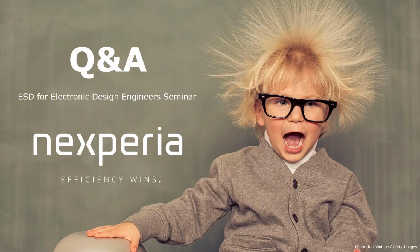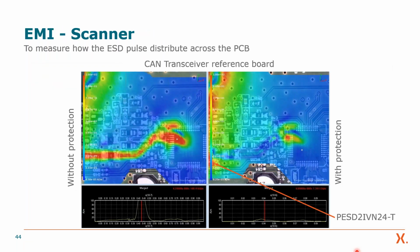Yeah, then Lucas, can you go back? There's a question on the left corner why it's red. So the reason, if you compare left side and right side, you will observe that on the right side with protection, there is less current at the IC, but there is a bit more current on the top of the PCB. And this is because there is the ground connection of the PCB and the current has to flow somewhere to ground.